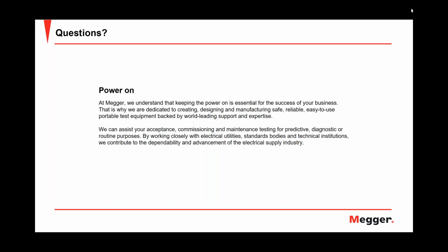And you can see the difference when you do fault location. That's a whole different premise. Henning just explained the cable test, the withstand, as it is heavily regulated in various standards. But in the fault location, in the most simple fashion, you have a small cable fault location system with you, maybe one of these micro thumpers, which has multiple fault location methods, and its source is a DC source. So you have to do this first step as a breakdown test with the DC source.